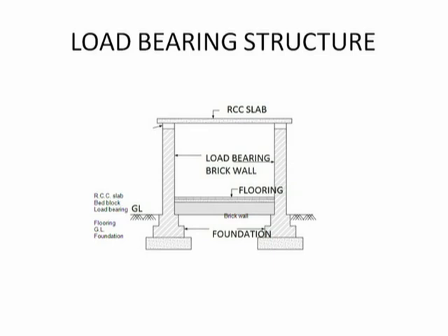This is a picture of a load-bearing structure. Here you see the two walls are constructed. These walls are responsible for the transmission of the load. The load of the RCC slab is being transmitted to the foundation through the wall.